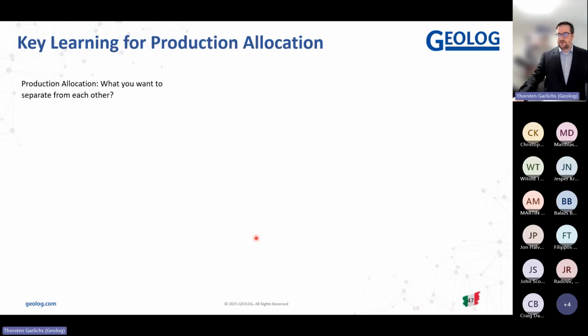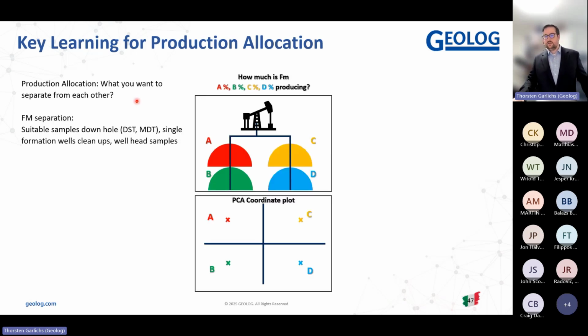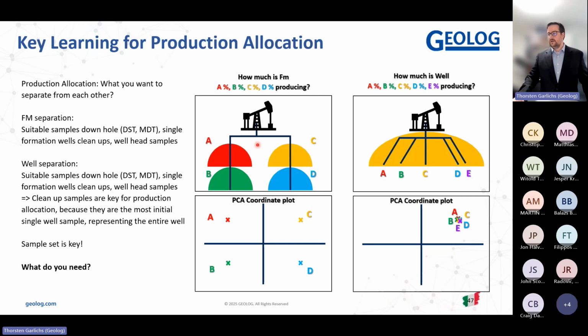The key learning from this Maria project is: what would you like to separate from each other? Is it formations? So what is suitable to do the formation separation? Here you can normally use DSTs, MDTs, single formation wells, cleanups, and wellhead samples. And with formations, you have in many cases a quite strong, very clear separation. The differences are not as high as in the Maria case.